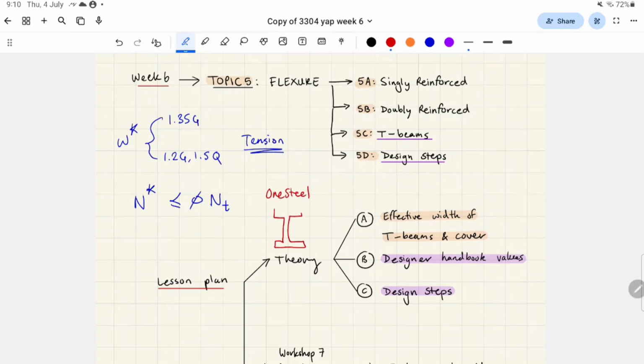You went onto this website called One Steel, and you can select from a variety of I-beams, for example, and those have specified dimensions, like widths and depths, and all these properties, like Ag, the area. You put it into the formulas for your capacity, and you check whether it passes the test, and if it does, then that's all good. That's what sizing a steel member is all about.